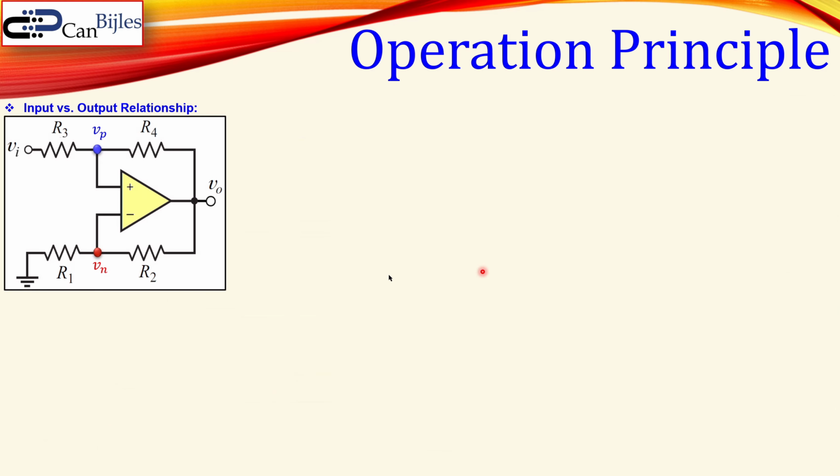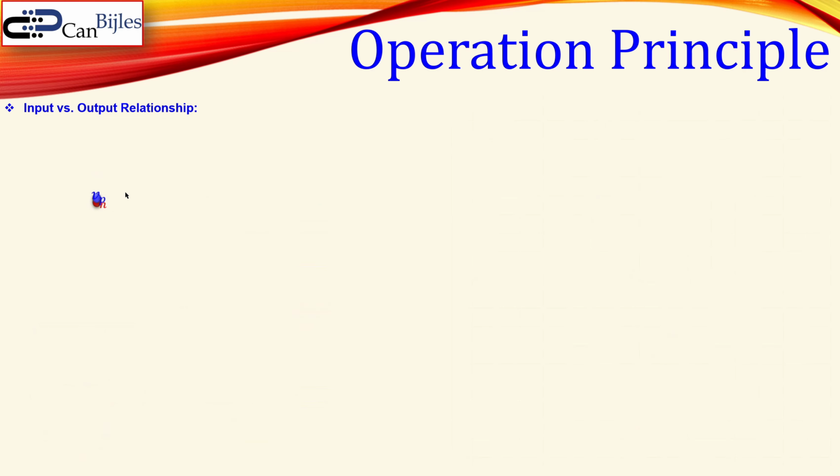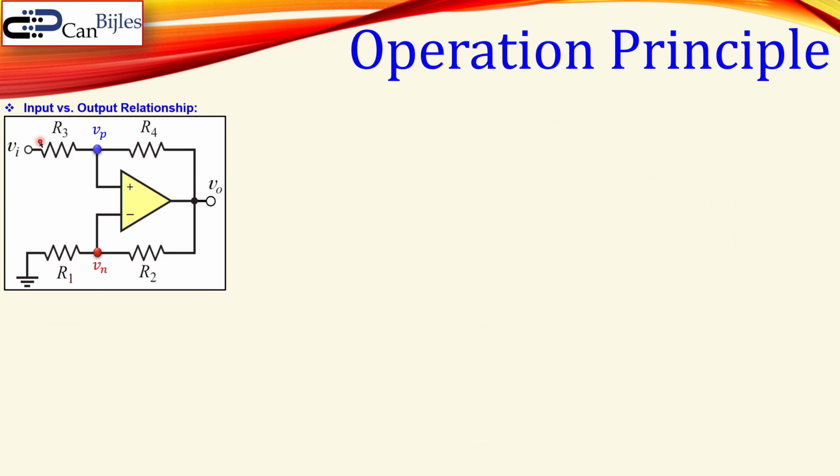Okay, let's now also look at the situation where we switched the input voltage, because it was before that the input was here. Let me go back, you see that more clearly. This was here, so the input voltage goes through R1 to the inverting input of the operational amplifier. And if we now switch that, we can also do that like so, and then ground this part. So it's actually just a flipped version.